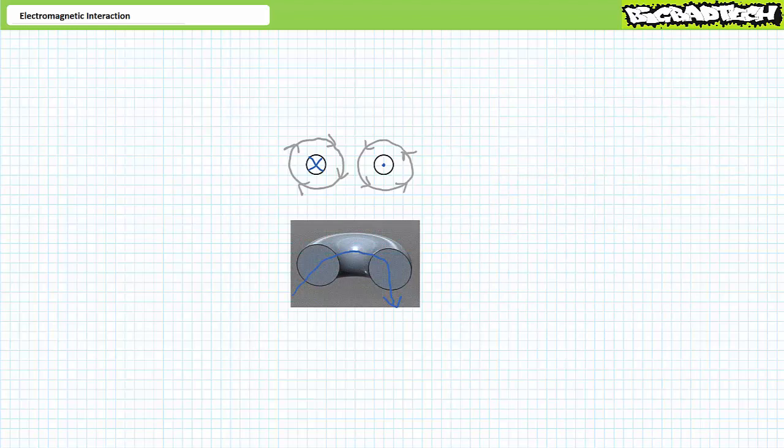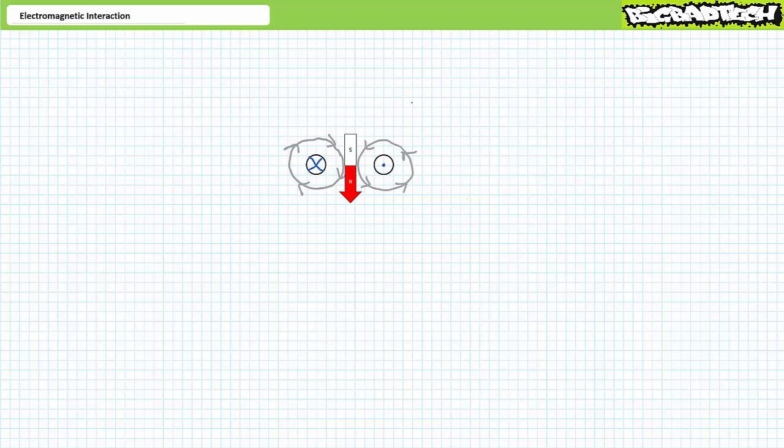Now, rather than think of these 2 current-carrying conductors as separate unrelated entities, think of them as a cross-section of a current-carrying loop of wire in three-dimensional space. Current comes into the loop on the left and out of the loop on the right. As a result, the field on the left rotates clockwise, and the field on the right rotates counterclockwise. Notice how the two magnetic fields mutually reinforce each other at the center.